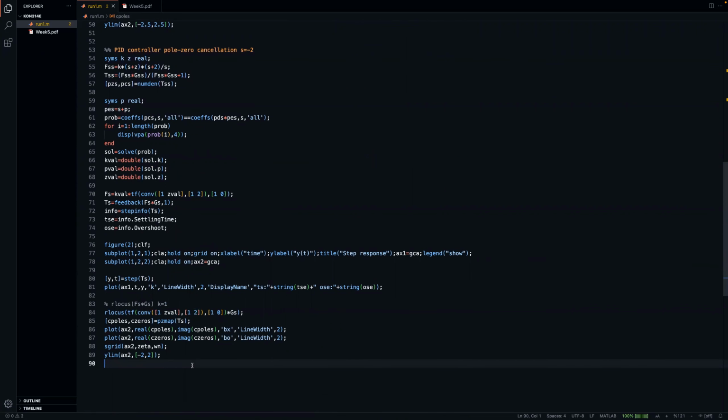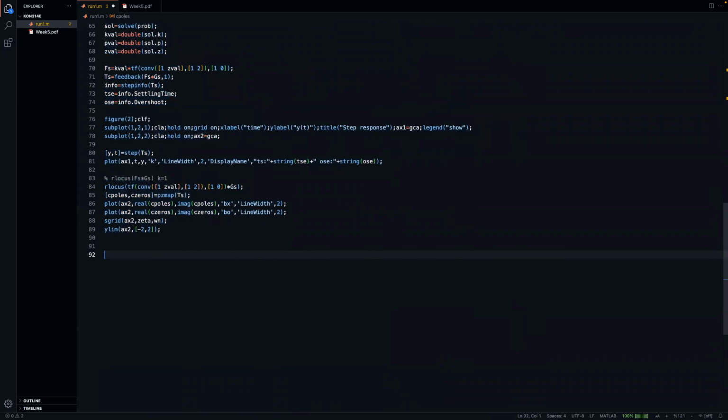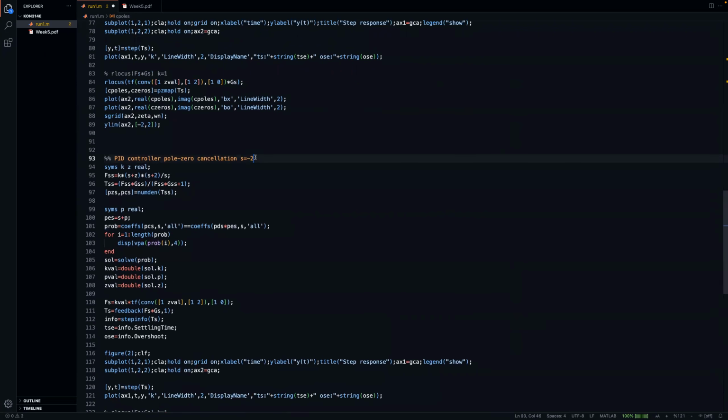There's another pole-zero cancellation setup that I might want to look at, going a bit further and canceling out both -2 and -5. Since you have 3 poles, and one of them is at the origin, I wouldn't touch that one.